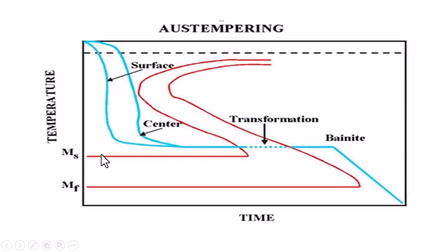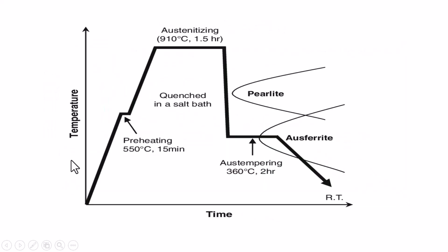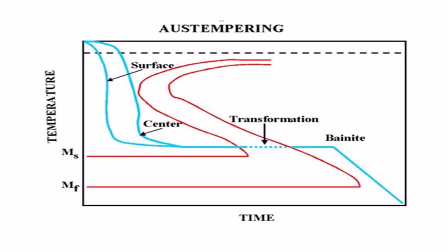This is martensite. Martensite is the hardest form of the steel. There is a martensite start temperature and a martensite finish temperature. That means if you take austenite in the iron carbon diagram, the austenitic range, gamma iron, that is a stable condition. If you suddenly cool it by quenching in water, you will get martensite.